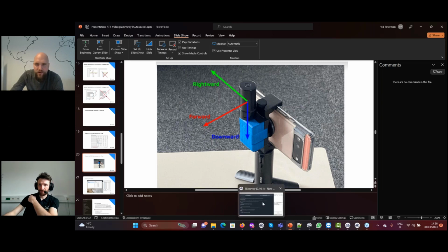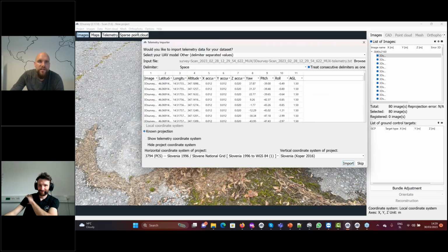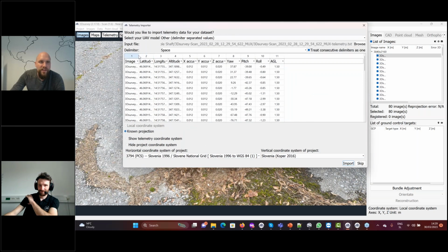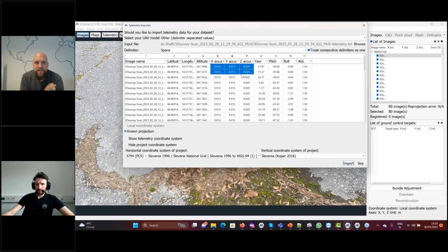Okay, in the meantime, while I was speaking, this thing has finished processing. So here are the frames that were automatically extracted and latitude, longitude, altitude informations. So the GPS device, it actually reports the accuracy of about 1 centimeter. Because this position is calculated once per second, to be honest, I have a feeling that we get slightly better results if we manually lower this accuracy slightly. So we will do that later.